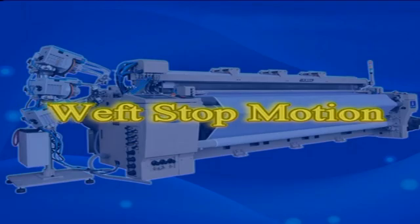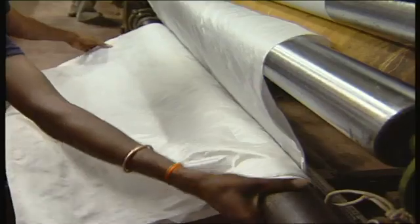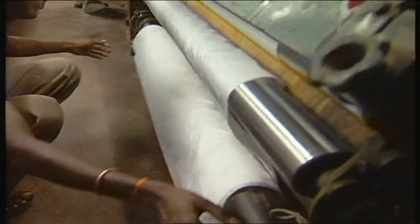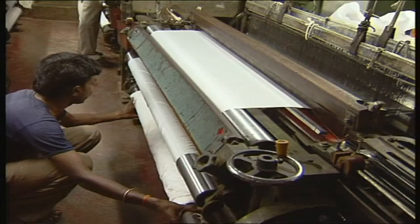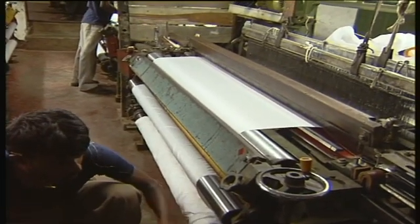Weft stop motion. The object of the weft stop motion is to stop the loom when a weft thread breaks or gets exhausted. This motion helps to avoid cracks in a fabric. Temples. The function of the temples is to grip the cloth and hold it at the same width as the warp in the reed before it is taken up.